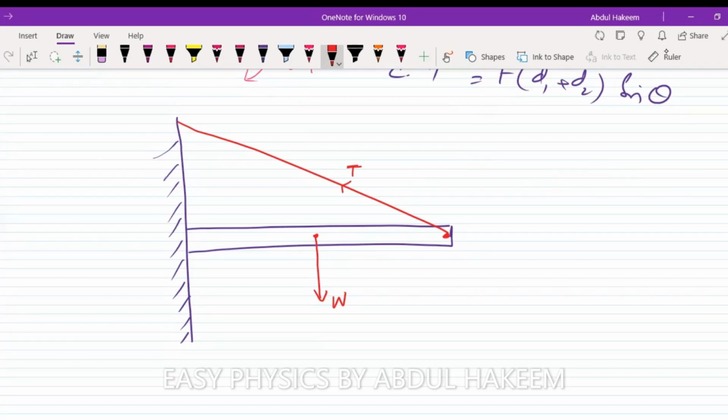If the forces are not parallel, do remember, then all forces acting in the system must meet at a point. Now, the third force, which is acting here, the reaction of the wall, must meet these two forces here. So this is the direction of that force. Because the resultant force is 0, resultant torque 0. So three forces will meet at a single point to produce the resultant torque 0.